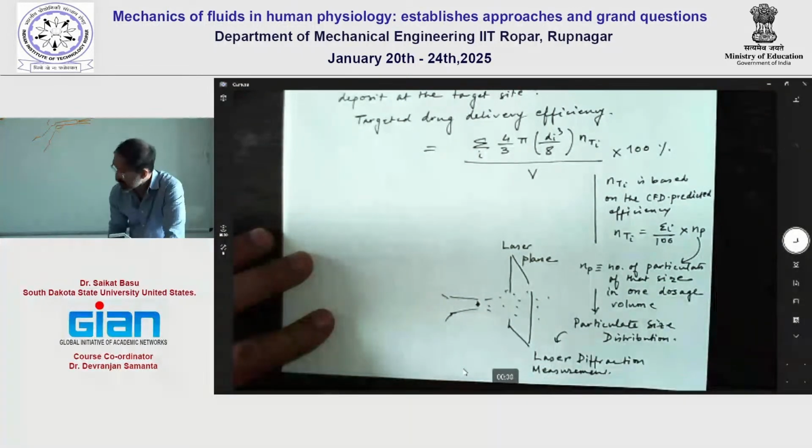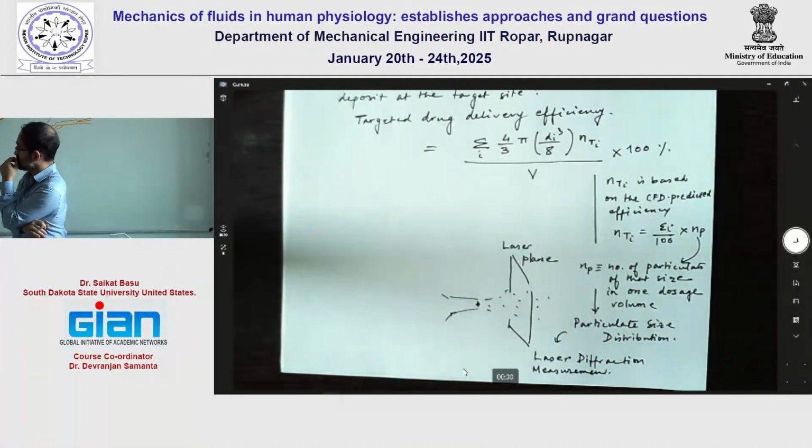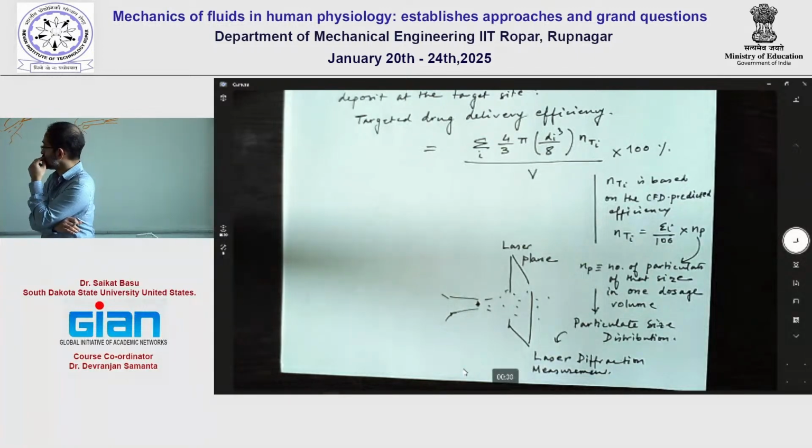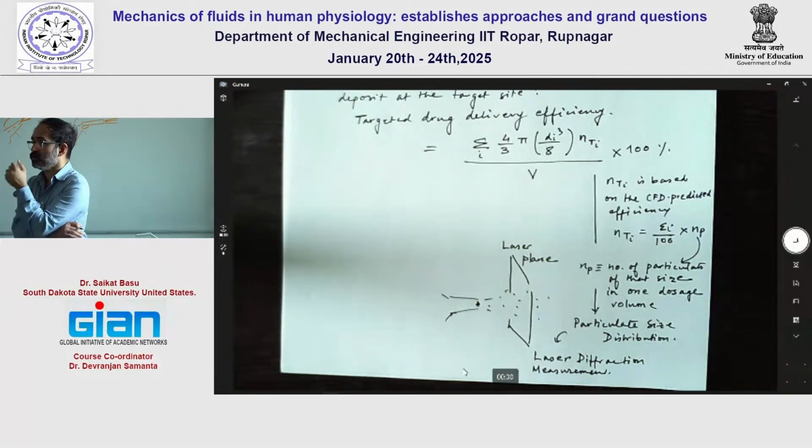Along with the size distribution that is passing through that virtual plane, we also get the speeds of the particulates as well. So if you move the plane closer to the nozzle exit, you will get the exit speed. We used 10 meters per second yesterday. If you go back and look at the papers that we typically cite in our studies, the range could be anywhere between 3 and 19.2 meters per second to be exact. We take just the middle number there as 10 meters per second.